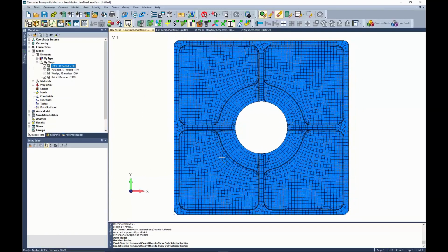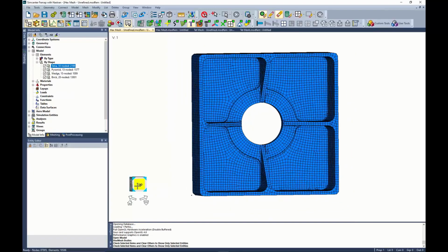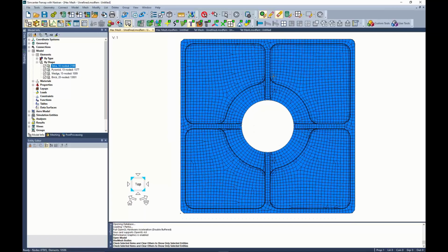So basically what this enables you to do now is, previously, if you needed a solid mesh of something, unless you wanted to spend a lot of time on it, you had to basically Tet bomb it. But now you can do the same thing with hex elements, also with a much lower node count, or you can increase the resolution for the same node count.